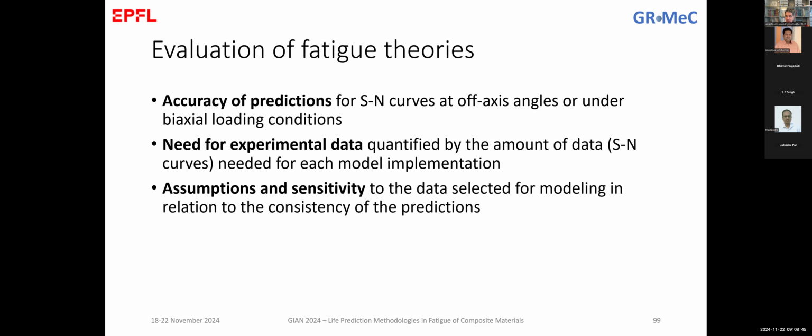But we've seen, for example, in the material with plus minus 45 degrees that we examined and presented yesterday or the day before, that the failure mode is mixed. We have fiber pullouts, we have delaminations, we have failures in the matrix, and depending on the loading, we can also have a failure of the fibers themselves. So these assumptions are nice, but they are not always validated by experience.